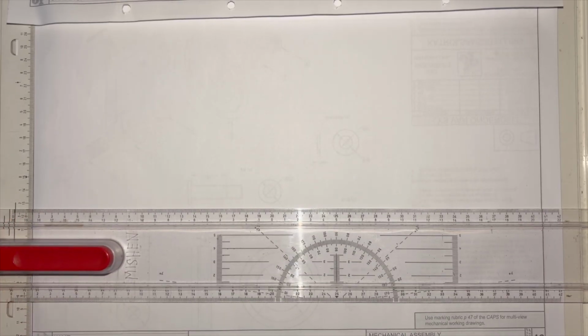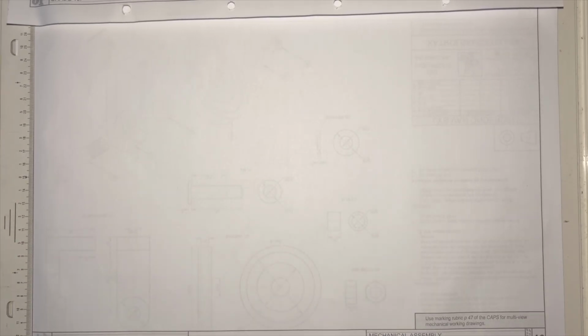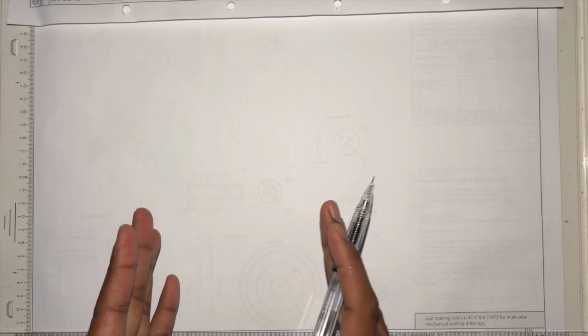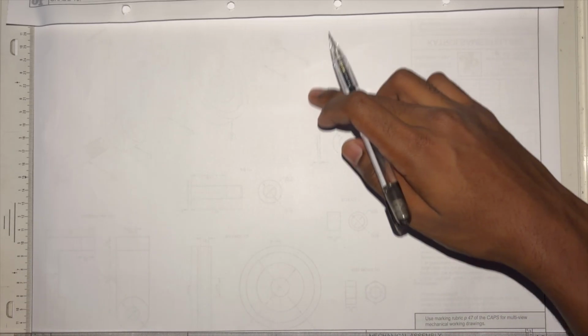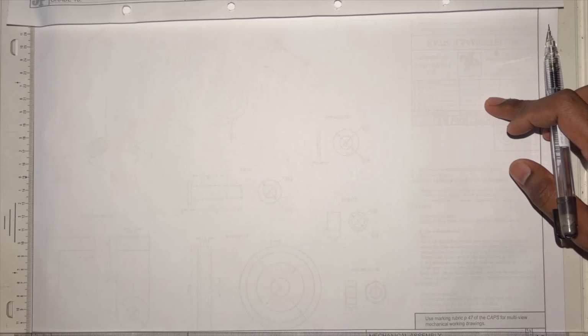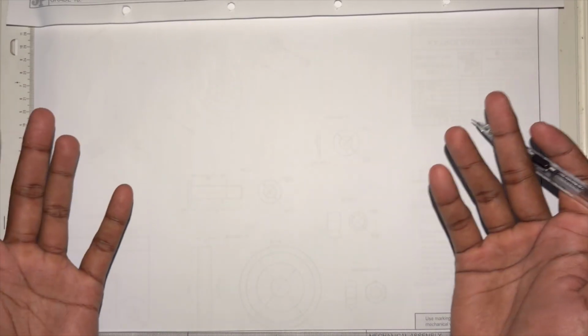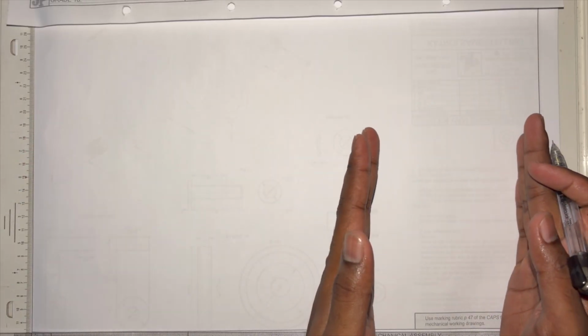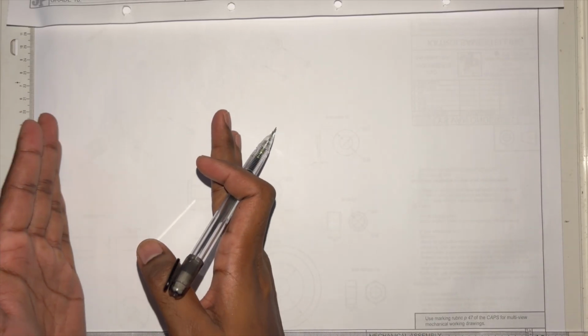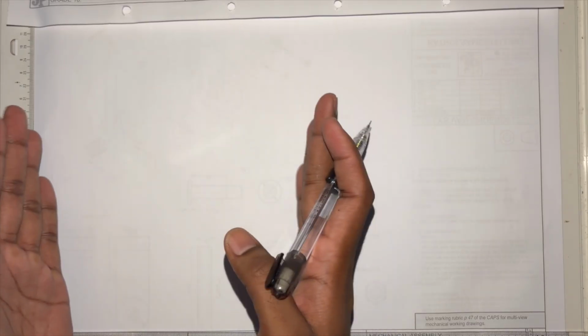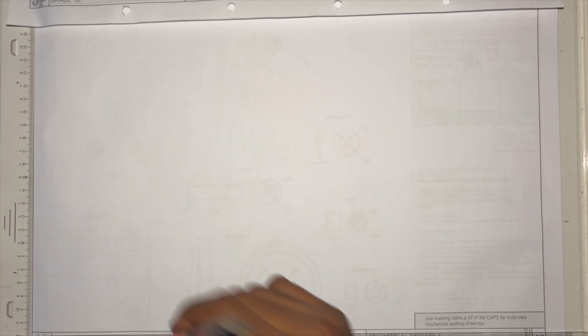Okay, so where on my page should I start? This is a blank page. Where do I start on the page? That's the next question. Okay, they want a sectional front view and they want a right view. Now clearly the right view is going to be on my right because we're working with third angle orthographic projection. So right view on my right, sectional front view has to be therefore on the left. Okay, so it's by a process of elimination. Because the right view has to go on the right, my front view has no choice but to go on the left. Okay, and we said we're going to start with the sectional view first, which happens to be the front view. So that's where I'm going to start, here on the left.